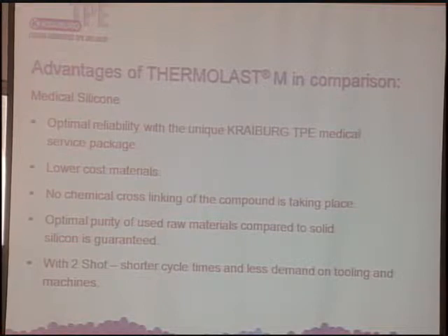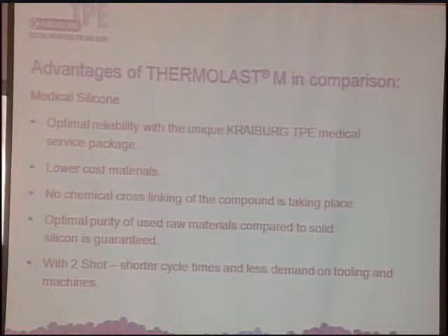There's no chemical reaction, low energy consumption, high line speed. Also, in terms of density, our material is typically about 0.89 gram per cubic centimeter to roughly 1, versus a higher density for the silicone materials, 1.2, 1.5, even higher. So for the unit cavity, you use much less mass of material by using the TPE versus silicone.